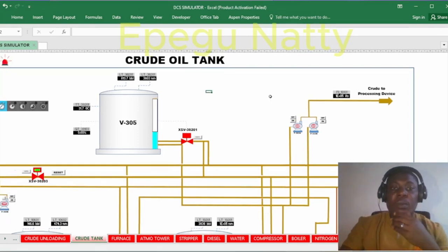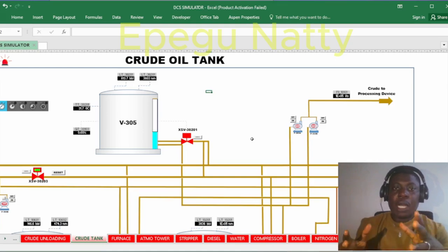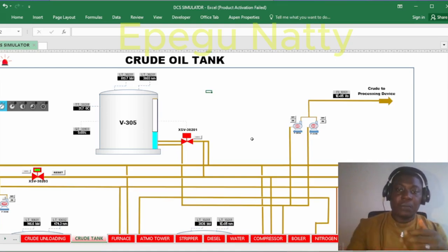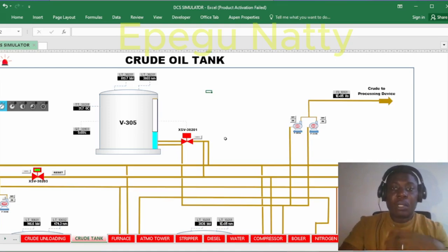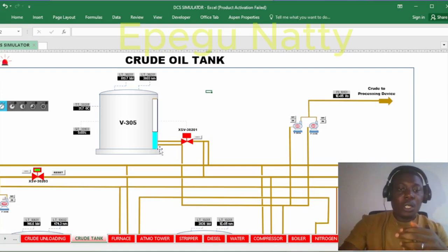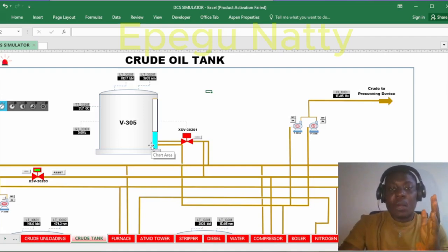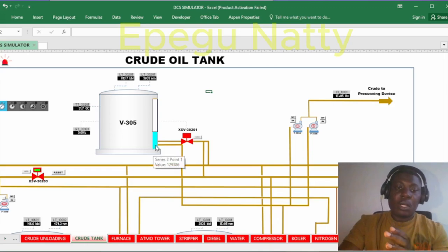Okay, so if you've been following our previous videos, you know that before you carry out a crude transfer operation, the first thing you need to do is your lineup. Now what do I mean by lineup? Lineup simply means that we confirm that all our lines are properly in conformity with what we want to do. So let's say we want to carry out a crude intertank transfer, and we know that we are using our discharge line, which is this other line without the shutdown valve. So you trace the line and ensure that everything is properly lined up.